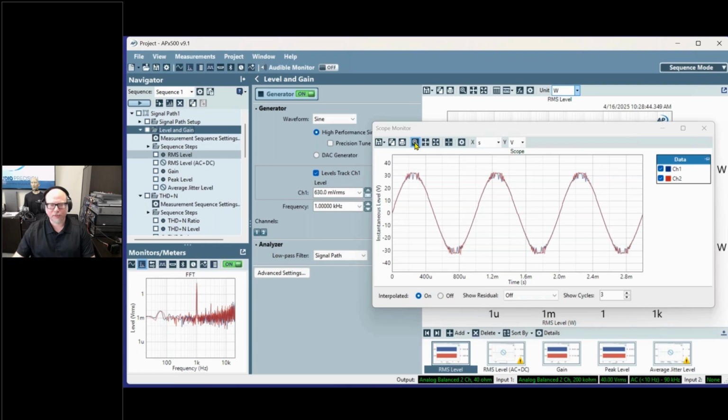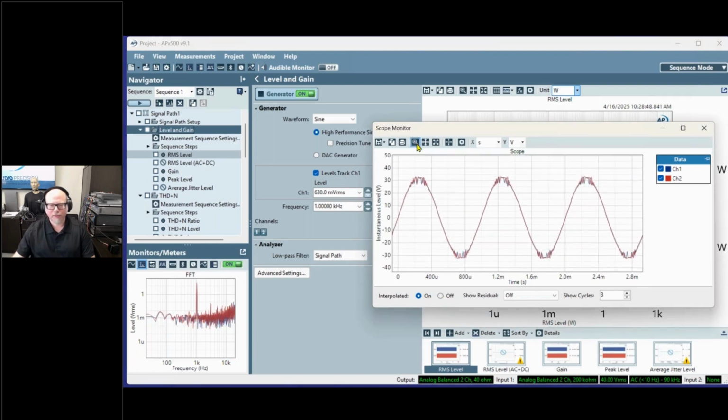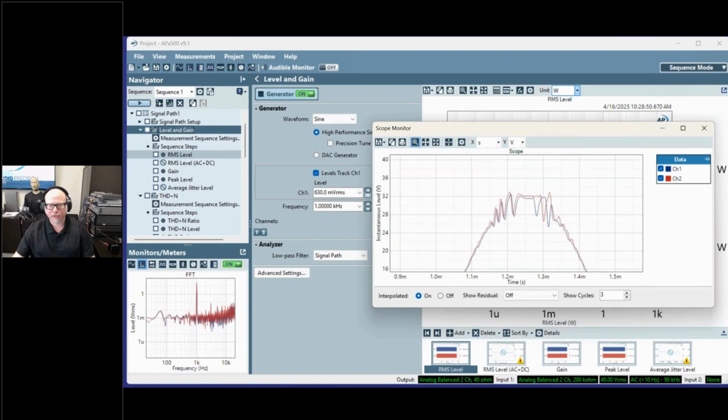The reason people use that clipping term is that when we look at the peak of our waveform, it's actually running into the maximum voltage of the power rail supplying the amplifier, and the peak of our sine wave gets flattened out.